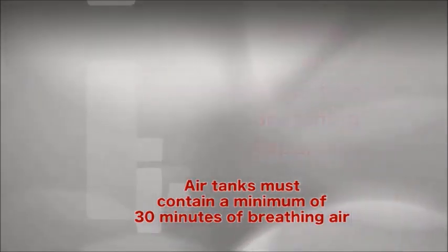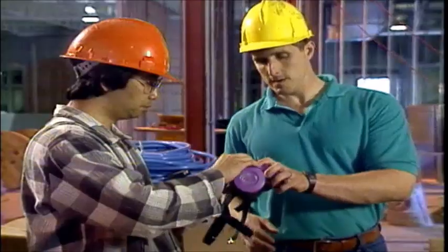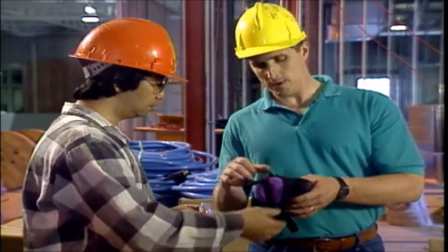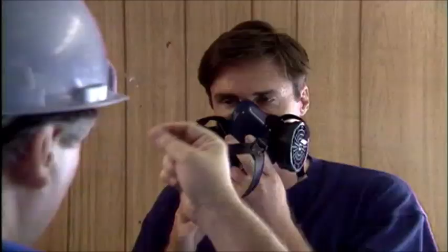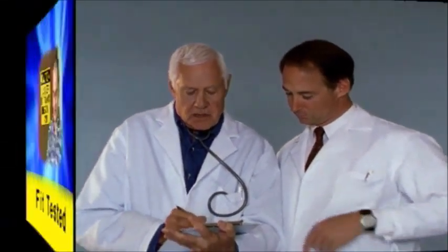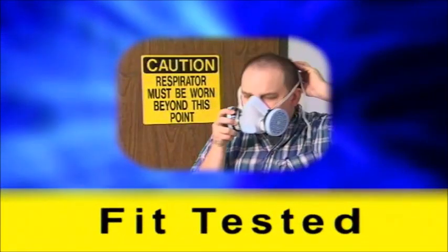An employer must provide training on the respirator and have a satisfactory respiratory program as required by OSHA. This program includes fit testing and medically qualifying all employees before they ever use a respirator. Before each use, respirators should be fit tested.